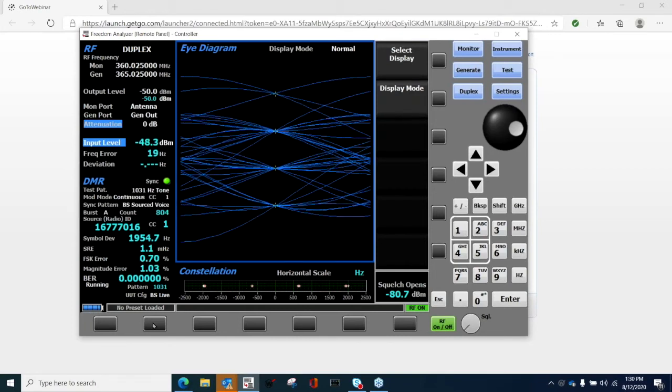So you have an F0 or a frequency programming, for example here, 360.025, and the symbols are shifting up and down from this frequency, in parts of minus or plus 1.944 and 0.648 kilohertz. Those transitions mean each symbol can carry 2 bits, and those 2 bits make the signal you're seeing here on display.